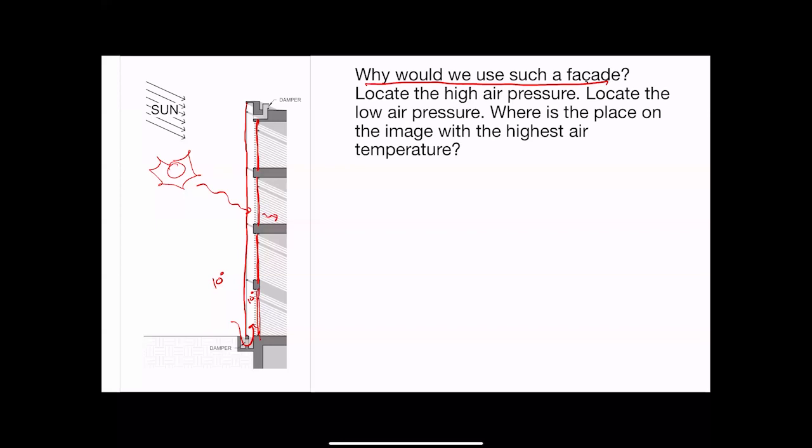building in the summer. But frankly, big buildings, and most of the buildings that have double skin facades are actually quite big. These big buildings, you guys know this if you take an Amber book, and NCARB doesn't seem to know this, but big buildings use almost no heat even in the cold parts of winter because they generate so much internal heat from people and equipment and lighting. But these days our lights are much less heat producing. So much less. It's actually one of the places we've done the best in terms of fighting climate change. Our lighting is just way more efficient than anyone could have predicted 15 years ago.